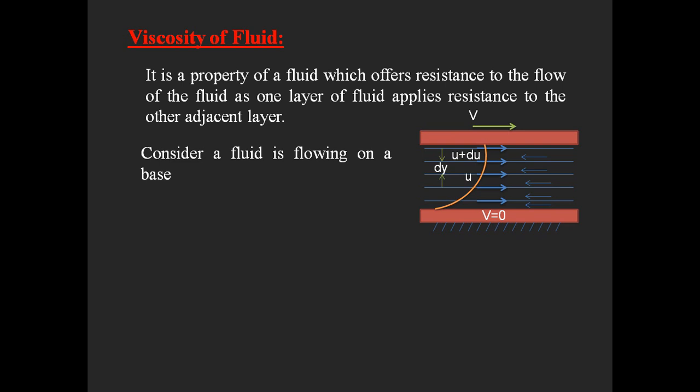This velocity variation is taking place due to the viscous property only, which is due to the resistive force. Next, I want to write the velocity gradient, which we can also call the slope of the curve we have obtained. How can we write it? Here the velocity variation is taking place according to the distance between the two layers, or as you go downward. So with respect to the displacement or distance between the two layers, the velocity variation is taking place.